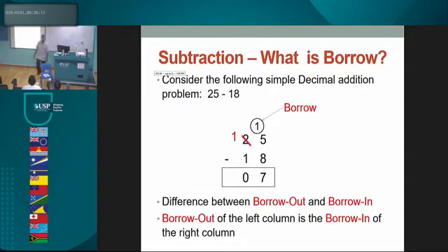Now let's start off with the basics. If you wanted to do 25 minus 18, you would first start from the least significant digit side. We're doing digital logic over here. We attempt from the least significant digit. So we say 5 minus 8, and you say, oh, can't do that because 5 is a smaller number. In normal primary school mathematics, you go next door, to the digit one up. You do something called a borrow. You all remember this, right? You borrow a 1, and the 2 is left over with a 1. So you borrow a 1, so that becomes a 15. 15 minus 8 is 7, and 1 minus 1 is 0. But we don't write 0, 7. We just say the answer is 7. But of course, for the purpose of our electronics, we will get some zeros.